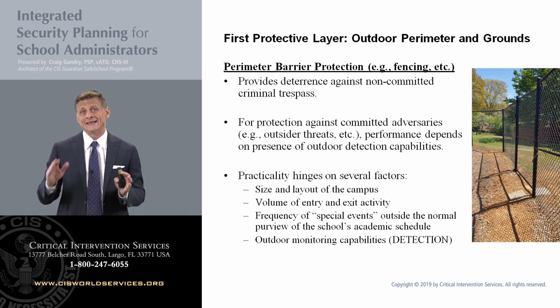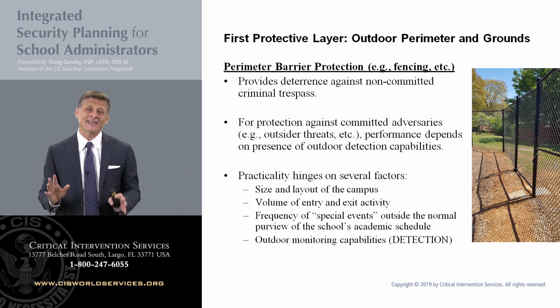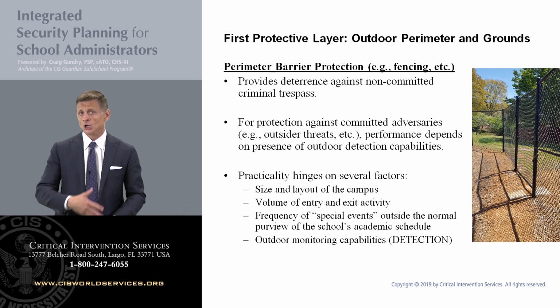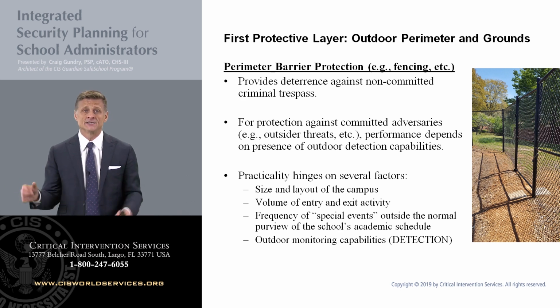Good example, a 7-foot tall chain link fence attached to a bottom rail with a barbed wire top guard, according to Sandia National Laboratories, only has a mean delay time of 8 seconds against an adversary with gloves. That is its true performance measure in a performance-based physical protection system.